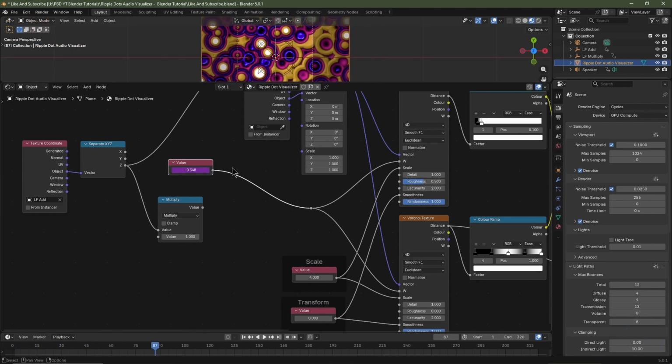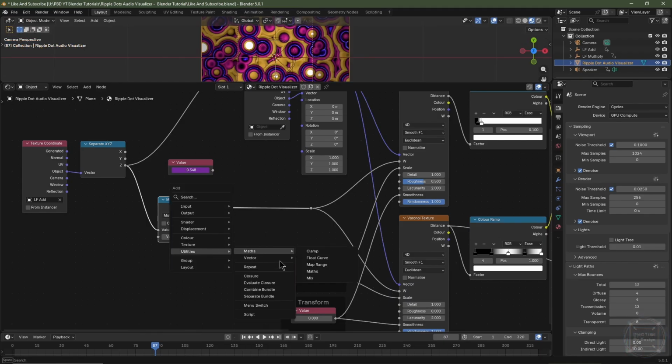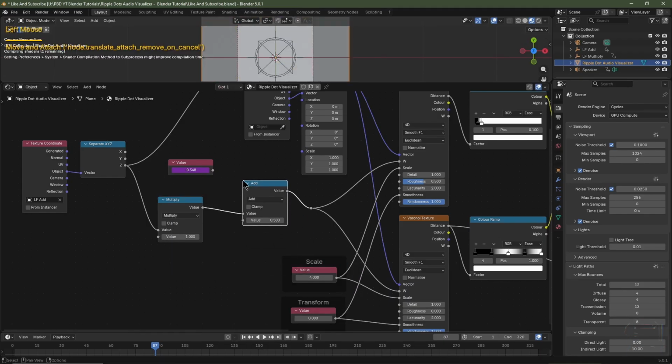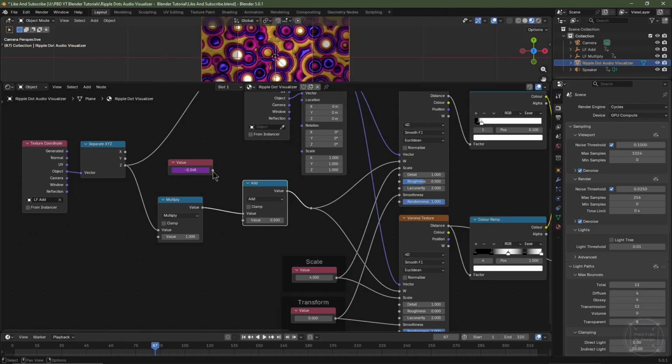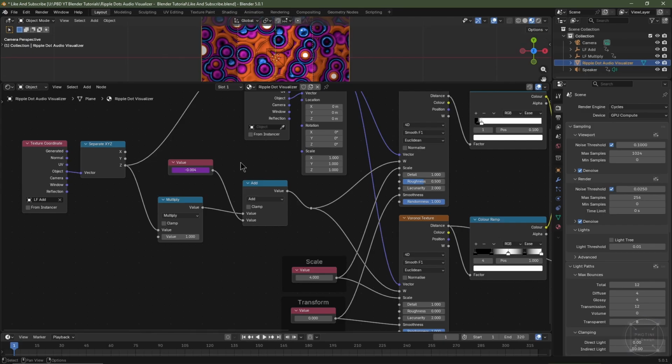But now I want to mix this in with the low frequency add function. So I'm going to take this multiply node and connect the value socket from this multiply node into the loop here. I'll then hit Shift A, go Utilities, Math, choose Maths, and pop that in between there. I'm going to keep it set to add, and I'll connect this value node into the bottom socket of this add node. And now, if I were to hit play, we'd get the benefit of this driver automating the warping of the W factor, as well as having the low frequency add function also triggering the W factor.